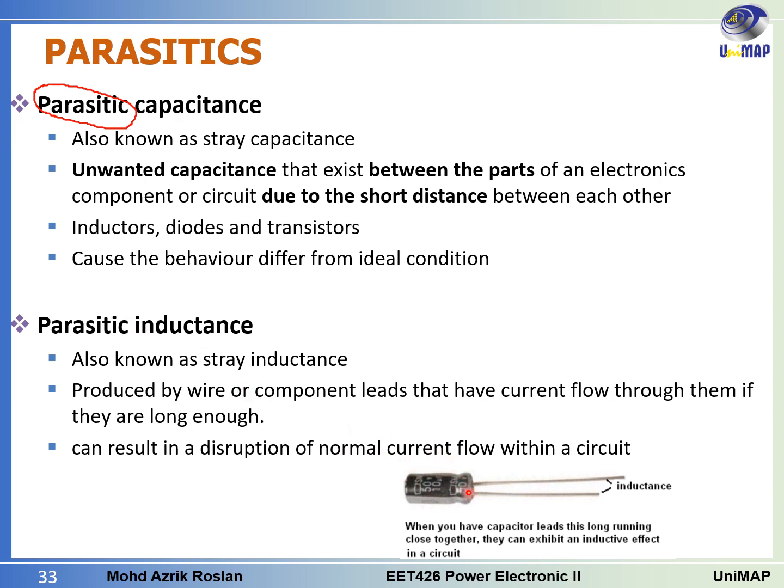You know that in a circuit board usually we want the components to be as close as possible to the board. Okay, let's say for this capacitor here, we want it to be as close as possible to the board, because we want to avoid having a long wire or long terminal here.